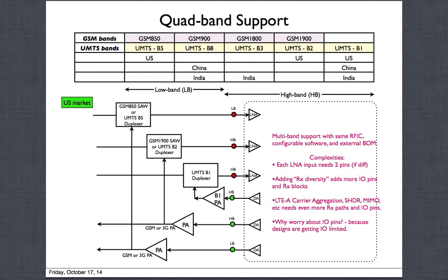So when we say how big is the die, the normal answer is, let's take all the blocks and do the layout, and whatever we can fit in some x by x dimension, that is our die area. That used to be true in the earlier chips, where the die was what we call die area limited, meaning the blocks in the die itself are limiting the die area.